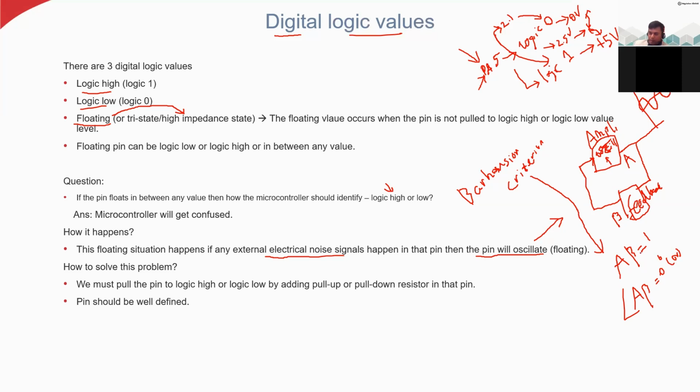In case this A beta is less than 1 or greater than 1, then what will happen? The oscillation will either start from somewhere and then go little by little and die, or the oscillation will start somewhere and then go higher and higher. But we do not want these two cases. We want the stable oscillation in the oscillator, because we use the oscillator in all the microprocessors and microcontrollers to generate the clock signals. Okay, this is called oscillator.